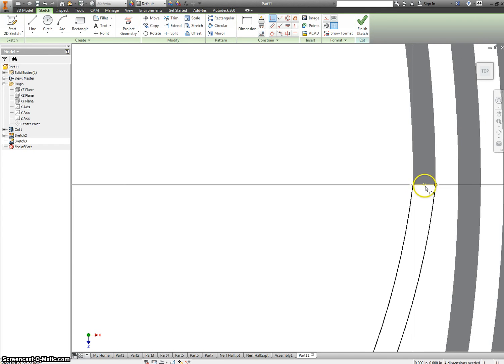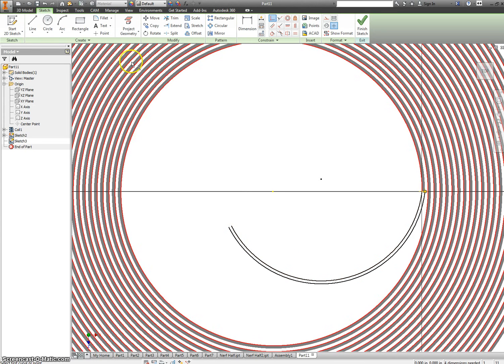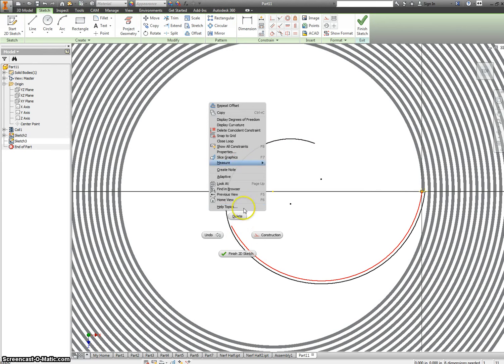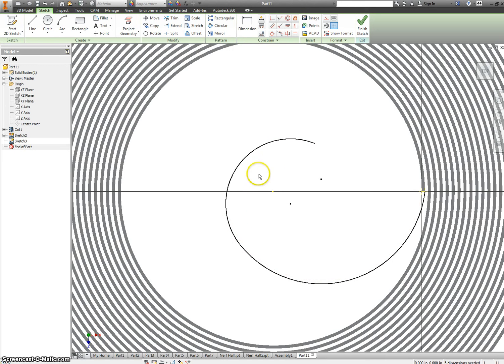Make sure those line up with the previous geometry. If I make multiple arcs, I want to make them tangent to each other so I don't have issues with sketching later. And probably be smartest to just sketch out the one before finishing and doing the other.